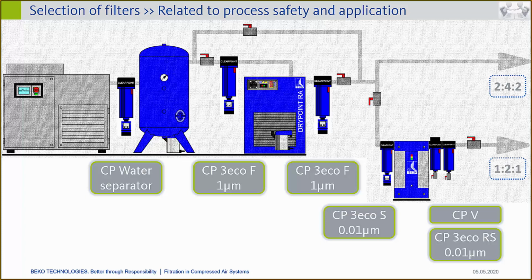And the more critical situation for the filter element is a too small velocity. From the performance point of view, it's easier for the filter element if you run an overload in flow rate than at a lower flow rate. Of course, we would win some pressure drop if we installed a bigger size of filter.